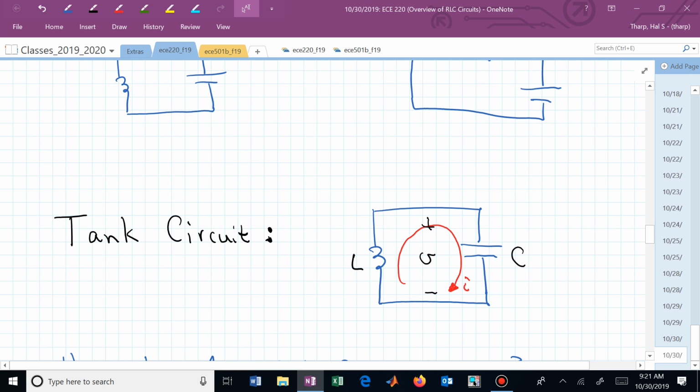But if I took out your voltmeter and put the positive lead up top and the negative lead at the bottom, I'm going to see the same voltage dropped across L and C in that sense, right? So that's the loose sense that I'm describing. Then when we wrote our KVL equation, the voltage dropped across the inductor is L di dt using the I that I've had there.